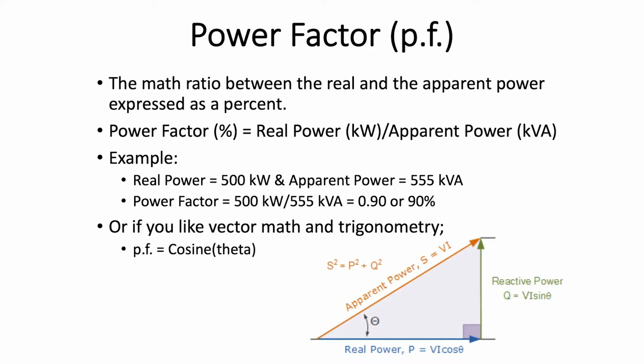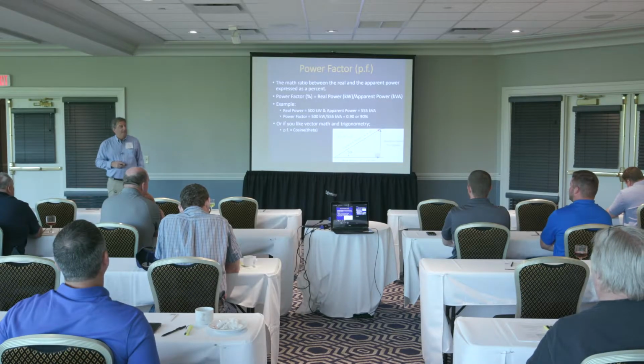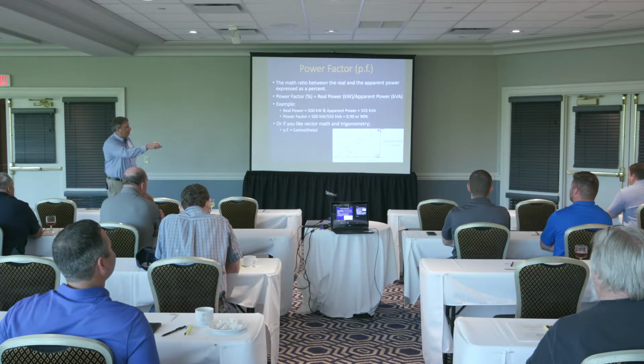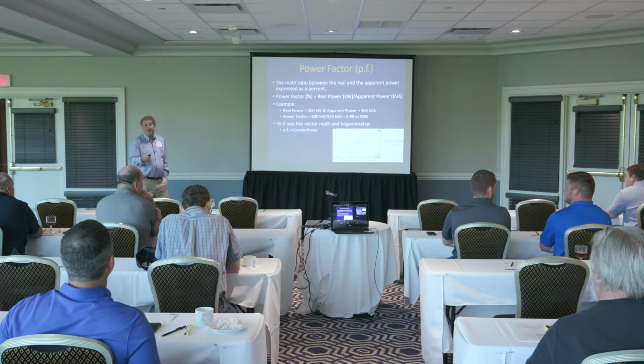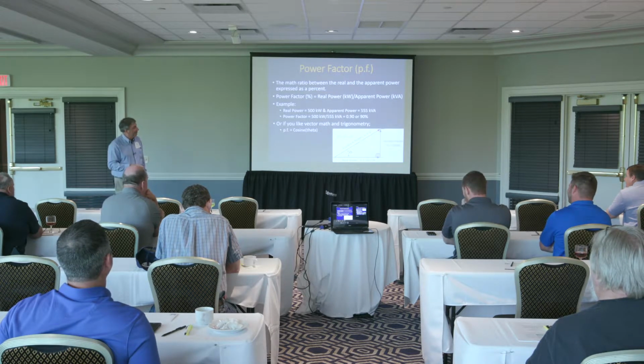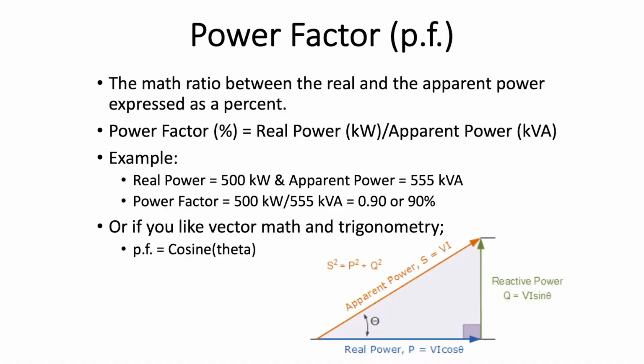Or if you like vector math and trigonometry, I can use the Pythagorean theorem. Terry, there you go. I'm sure you asked at some point a professor, am I ever going to use this Pythagorean theorem junk? With power factor, it's really important. So I've got my apparent power, my real power, and my reactive power. The math all works out, and power factor is the cosine of theta.